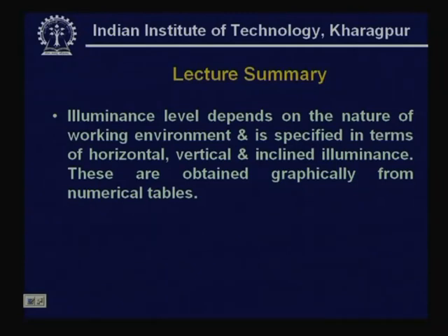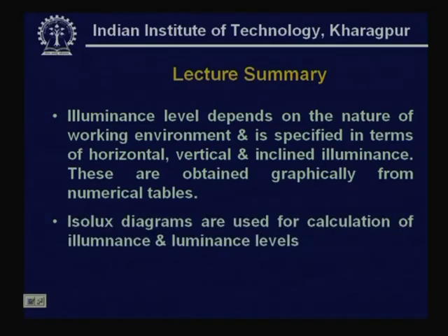This is the reason why, in good large conference rooms, on the conference table, to the extent possible, the luminaire arrangement is made as close to a sheet as possible, which may be by way of a matrix of incandescent lamps or CFLs or a large number of fluorescent lamps with a single diffuser.